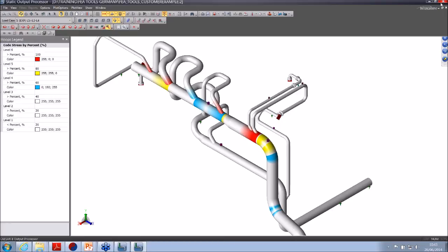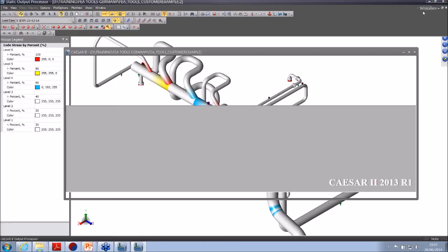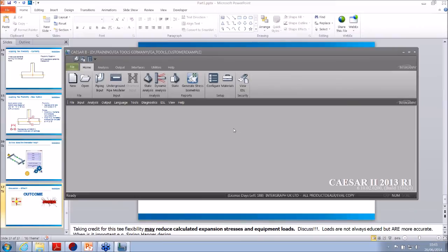Now, for those of you that are following along, if we run this through the FEA translator, it's going to take around 15 minutes to run. There are 11 intersections which need to be analysed, so it's only around just over 1 minute per intersection. But let's set the FEA translation going, and then we'll look at the model in more detail.